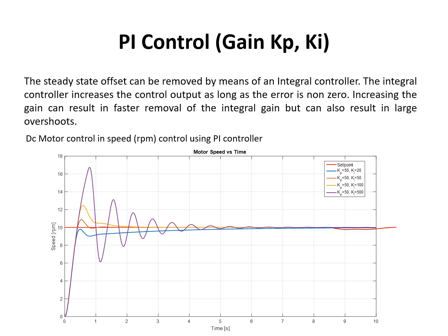And in general, the reason for this is because only when the graph goes through 0 do we have a 0 error value, and therefore we're not increasing the error term. So in this whole phase from here downwards, the error term is positive all the time because we have an output of 10 and the actual measured value is lower than that. So we have a positive error term and it accumulates error. So by the time we get to here, that does not necessarily mean the integral term is 0. That means we've accumulated a lot of error up to this point.